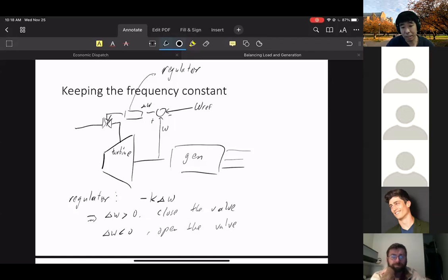Is the process always automated? Right. There are no humans in the loop in this. So you code this into the regulator. You have a microcontroller basically running this regulator, and it's an automatic feedback control. So there are no humans looking at this. For power systems, there's nobody looking at it. It's not worth the effort to have somebody looking at this regulator. There's nobody tuning this by hand. You basically just let this go, and this will keep the frequency roughly constant.